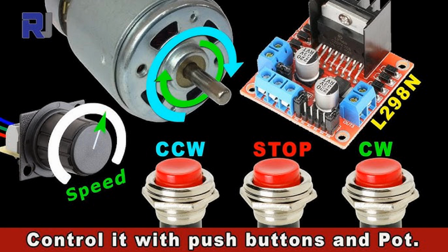9. Conclusion. Universal motor drivers are essential for controlling universal motors, which are widely used in applications where high-speed operation, compact size, and simplicity are key requirements. These drivers use methods like voltage control and PWM to manage motor speed, torque, and direction.